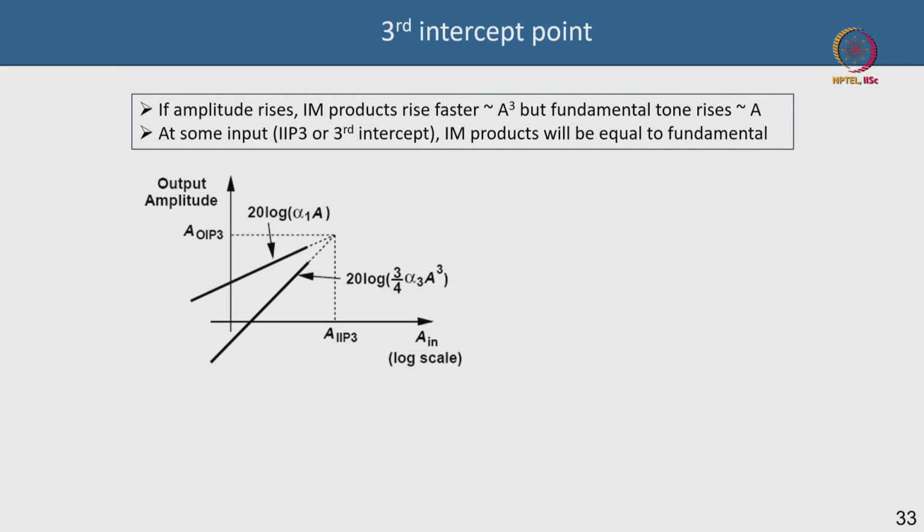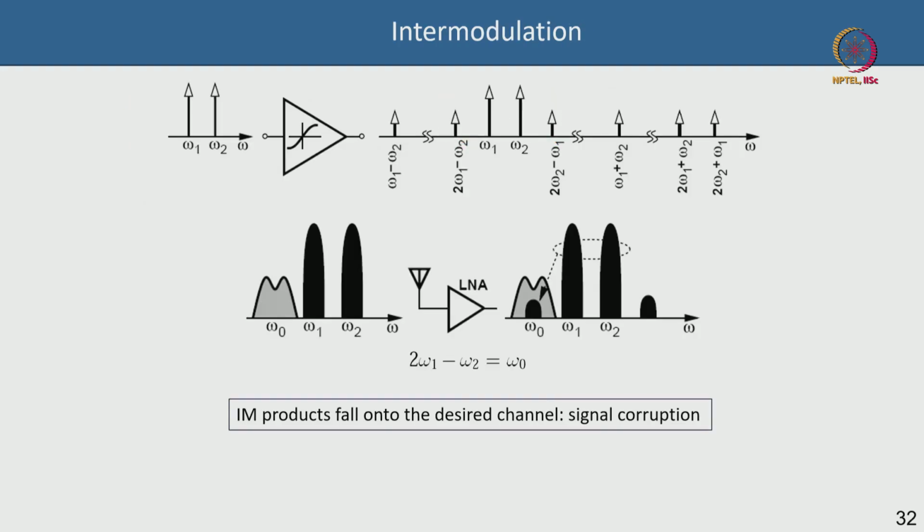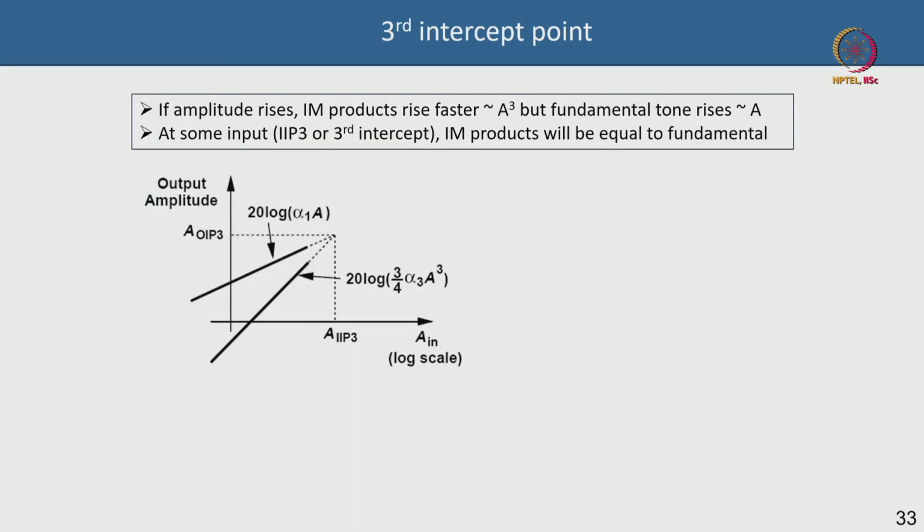Again, for intermodulation distortion products, or a two interfering situation, if you recall, these two interferers are there. What is going to happen is that you are going to lose power on the third order term, the nonlinear term. This is your third order nonlinear term where the power is being lost, and this is your fundamental desired signal where you want all the power to be. The x axis is the input power level, and this is a log scale.